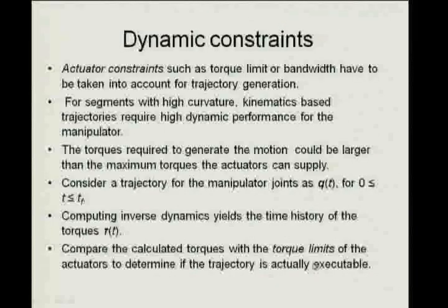Now, when we did our trajectory control, we said that given these q values I want to go from here to there, I just spliced it up, interpolated in the middle, and I came out with a set of q values. I never asked can the actuator produce the torques, and we saw, for example, when we are doing the blending, that if I decrease the interval too much, then the acceleration goes very high.